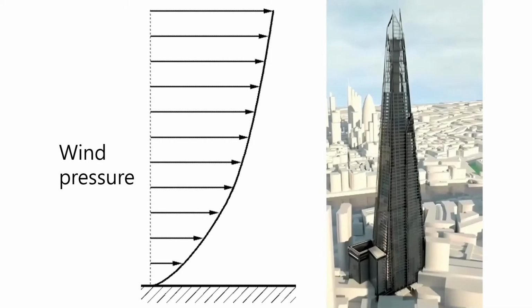There were many problems in constructing the spire. At this high height, lateral load such as wind load must be considered, because wind pressure gets stronger as height goes up. Actually, in strong wind, the Shard is intended to move up to 50 cm.